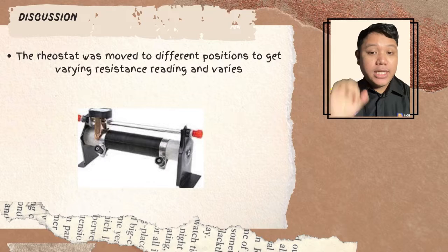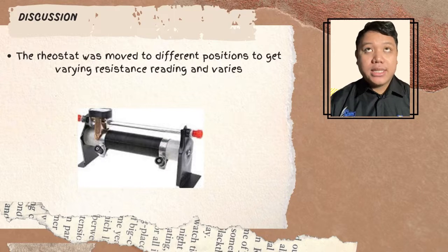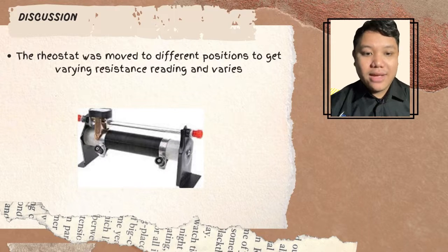Next, table 3.1 has the information of the datasheet and information regarding the site of the PV module. The maximum power is 345, open circuit voltage is 46.37 volts and short circuit current is 9.67 amperes.